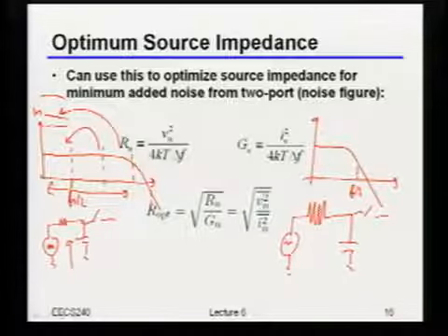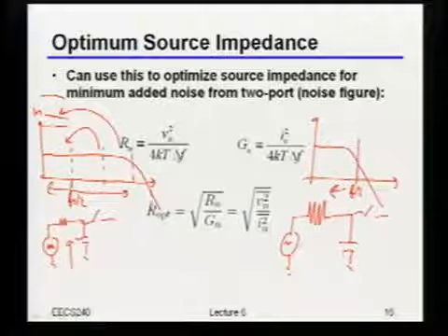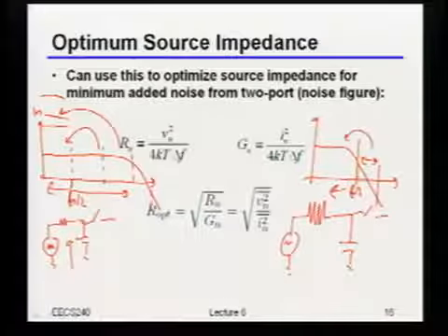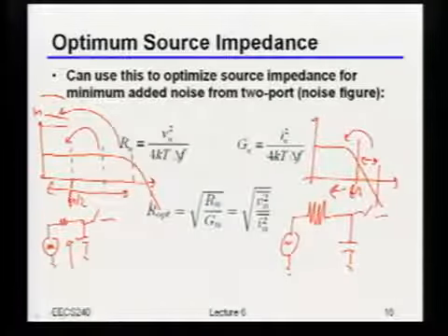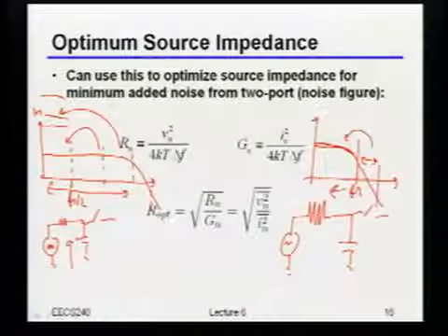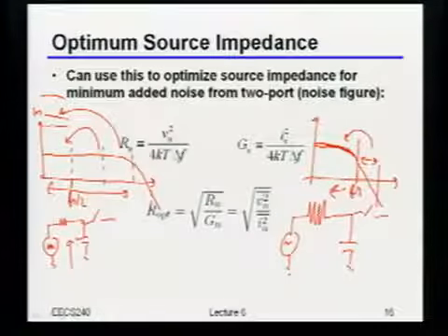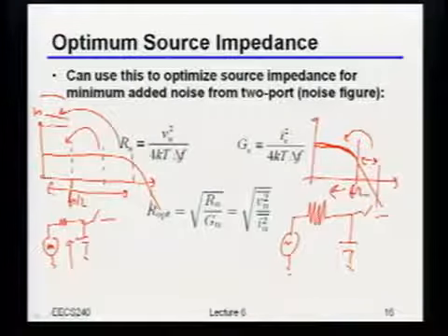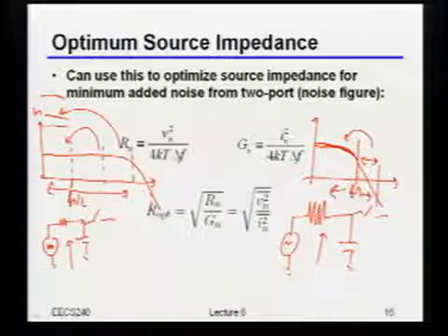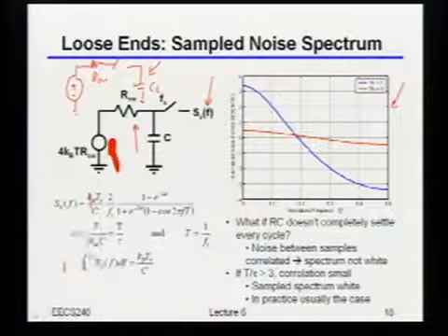No, right? Because I would take this chunk, and everything to the left over there didn't change any, right? Then I would take this next chunk over here, and when I fold that back, that's kind of small, right? But basically it's going to add just a little bit of curvature there. But since I've already filtered it before I even sampled, now I'm definitely going to have a low-pass shape over there, right? And obviously, the further I push the sample rate relative to this bandwidth, the more low-pass it's actually going to look, right? So that's basically what this plot right here is showing you.